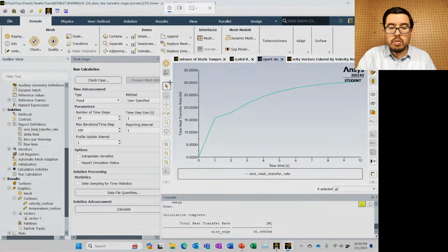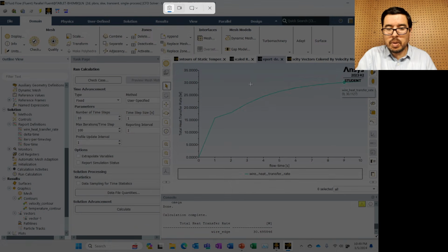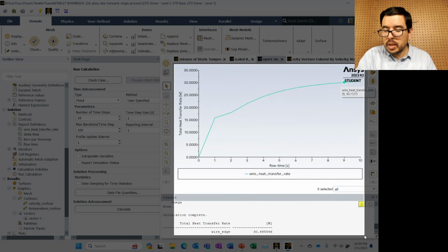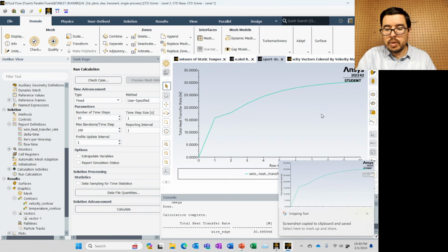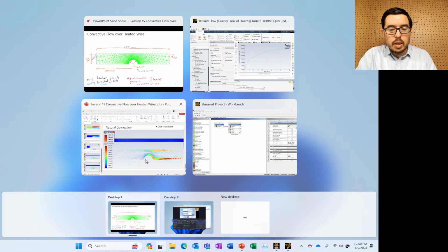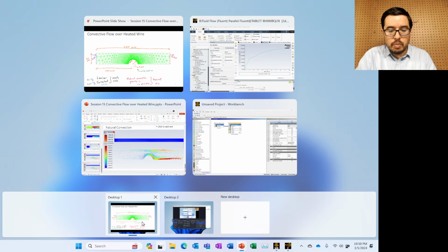All right, so as we let this simulation go, it did go up. So even though we had no velocity specified on the left side, there's still that's 30.1. Maybe I would capture the whole thing here, because this is the calculated heat transfer at the end. And you could argue that we haven't necessarily run this long enough to fully develop, because there's still some slope. I mean, it's more or less flattened off, but this is a pretty cool result too. Okay, that for these conditions the heat transfer rate is comparable.